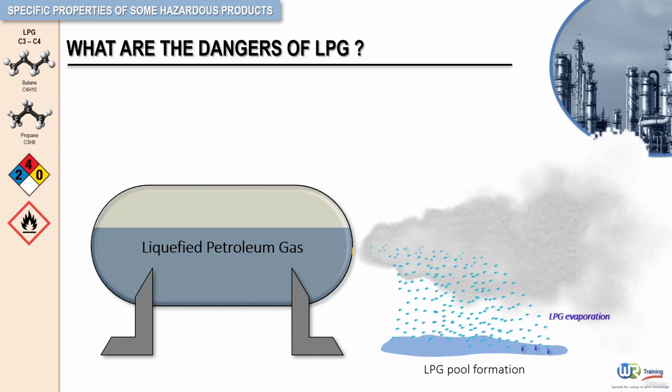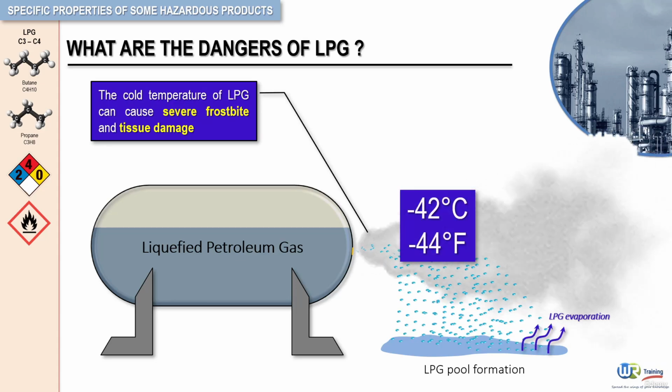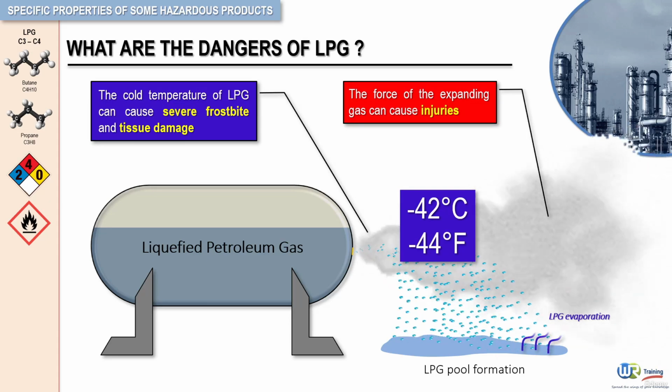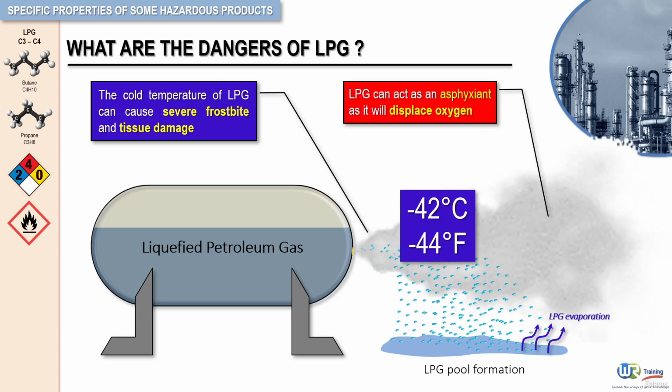LPG can also cause cold burns if in contact with the skin. The force of the expanding gas can cause severe injuries. In addition, LPG can act as an asphyxiant if present in high concentrations, as it will displace oxygen.